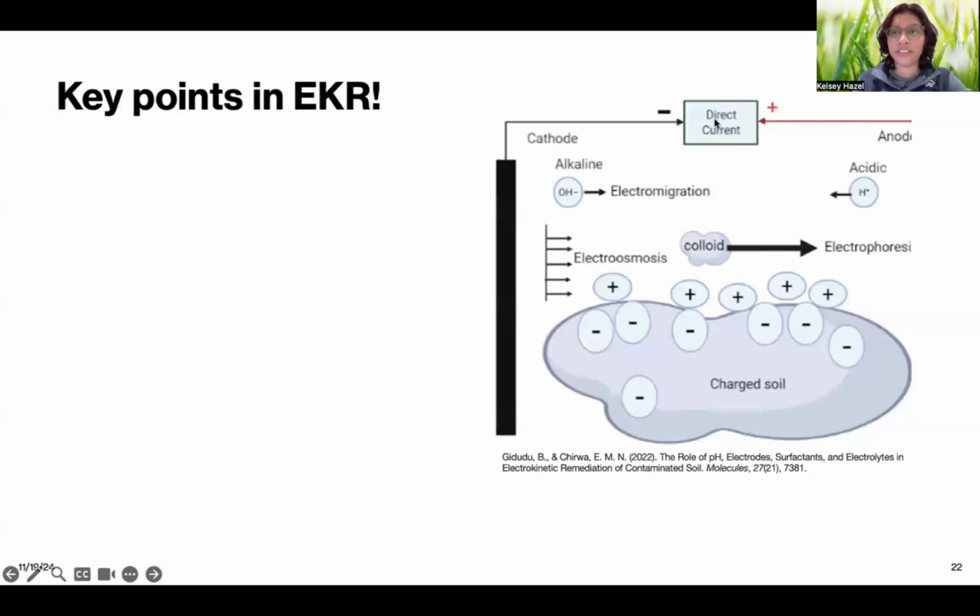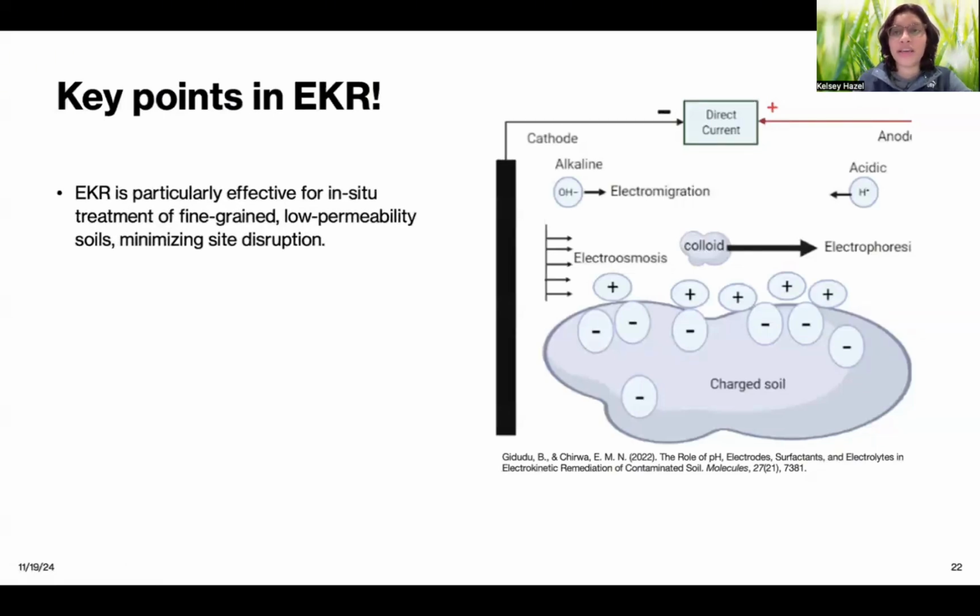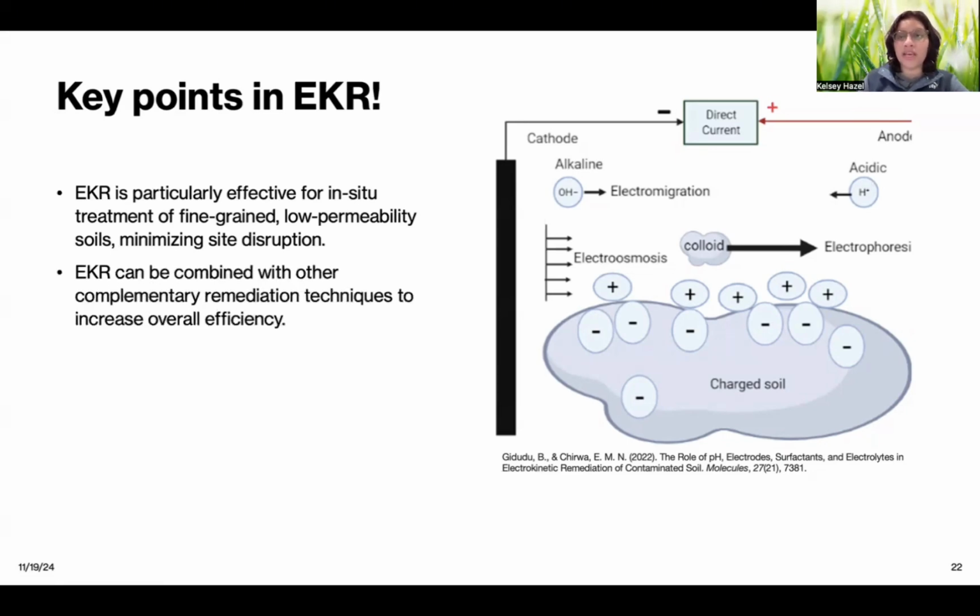Let's review what we've learned. EKR is particularly effective for in situ treatment of fine-grained, low-permeability soils, minimizing site disruption. Soil types include clay and silt. EKR is complementary with other remediation techniques and can be paired to increase overall efficiency.